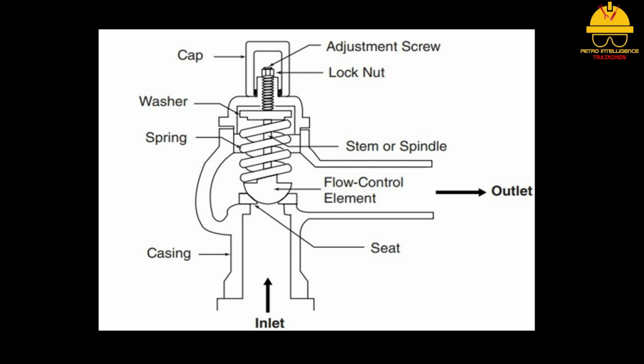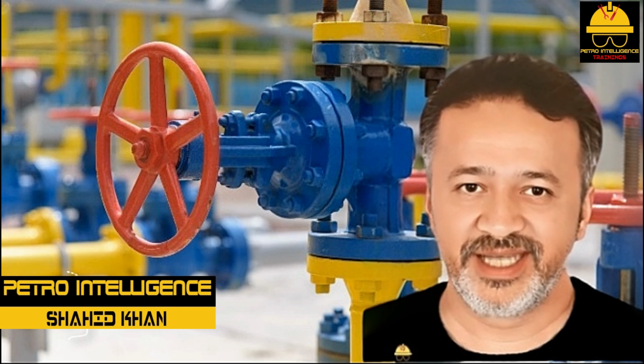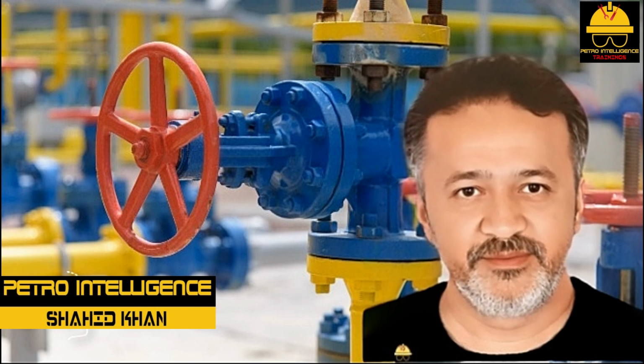A relief valve consists of the following components: a cap that protects the adjusting screw, the lock nut, and the internal components of the relief valve, an adjusting screw and lock nut, a casing or body, a spring and spring washer that hold a constant tension against the disc, inlet and outlet ports, a disc or plug, a spindle or stem that is threaded and screwed into the flow control element to guide vertical movement of the disc, and a seat. When a relief valve opens, it is relatively easy to detect flow through it.